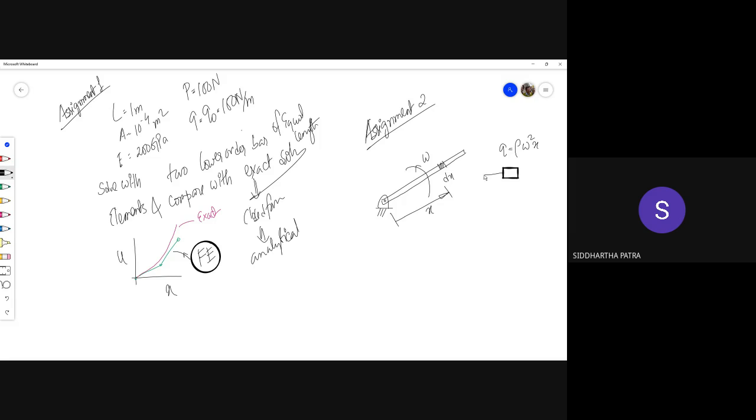You see, on this side, the stress should be sigma, and on this side, the stress on the bar should be sigma plus sigma prime dx, and together this should provide enough force for centripetal acceleration.